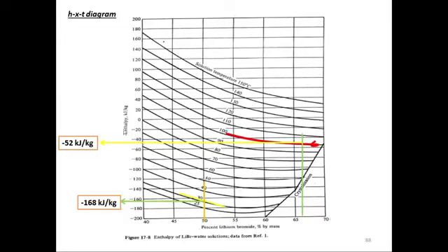Why minus? Because of the datum that we have selected. That is, water at 0 degree has 0 enthalpy, and lithium bromide salt at 25 degree has 0 enthalpy. So based on that we develop a scale. That scale is telling us that it is minus 52 kilojoule per kilogram. Otherwise you can argue that it is a scalar value, so why does it have a minus sign in front of it? But it is minus because of our datum line, the way we have selected the datum.